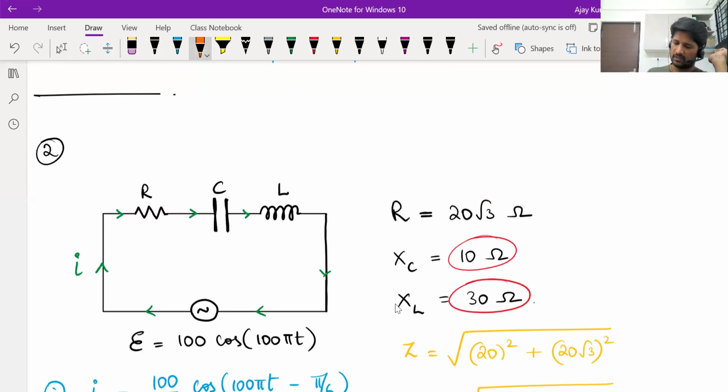Now, Rishi, you tell me, in an alternating circuit like this, suppose a voltmeter is connected across the capacitor inductor combination. How will you tell the reading of that voltmeter? Sir, first we'll calculate VC and VL. Okay, good. And then can we sub... No, but that won't make sense. Why will it not make sense? They are exactly out of phase. If one is positive, the other is negative, you have to subtract.